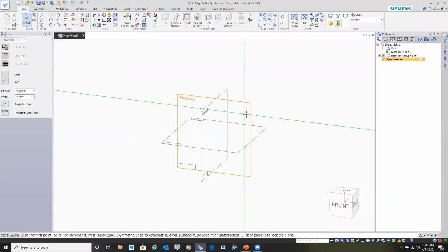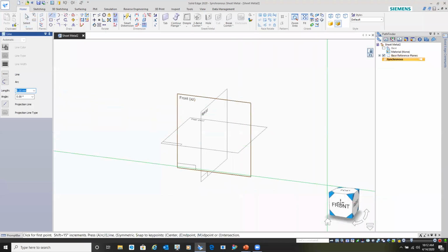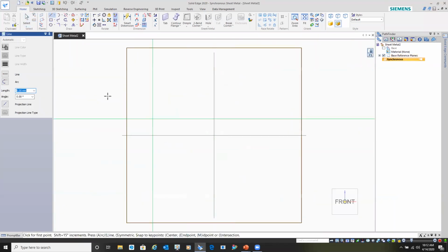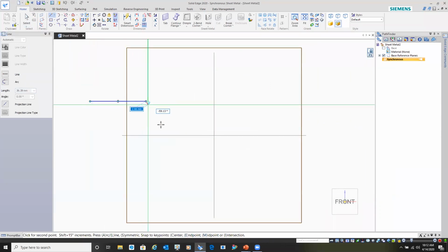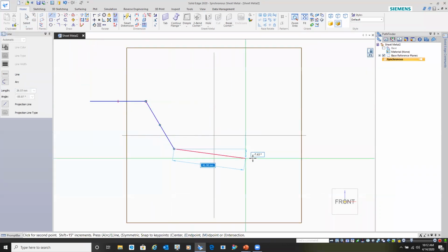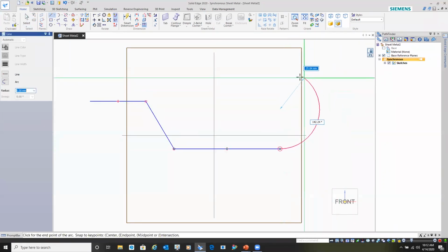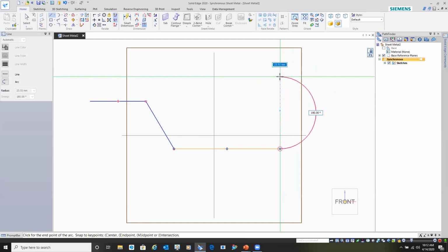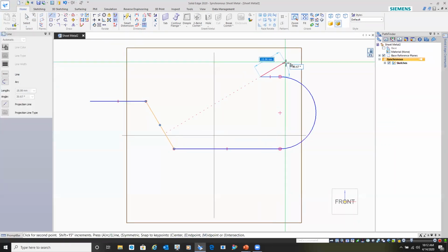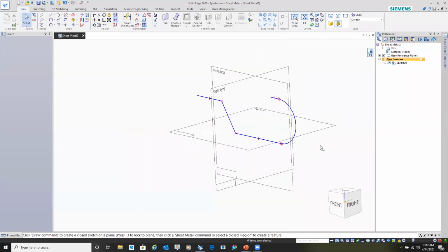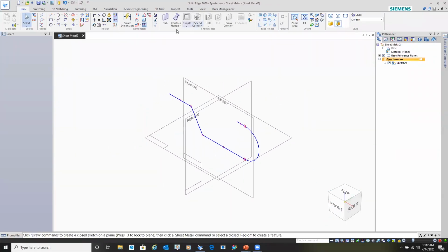And we do have to have an existing sketch, remember? So we're going to go in and lock a plane here, and we'll get the front view of this plane. And I'll just quickly draw something like we had on the screen there just a moment ago. Hit the A key to go into my arc. And then it automatically comes back to the line for me. That should be good enough. So there's my profile. And we'll go back to the home position.